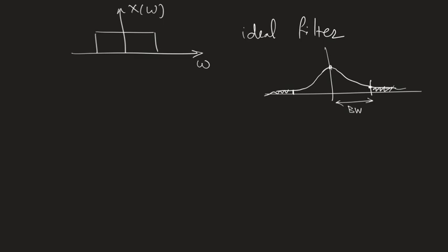Or when you discussed in your circuits the transient effect that happens due to switching on the circuit, you assume that after a couple of time constants, it decays enough such that you can assume it's no longer existing, and you are dealing with a steady state signal. You are no longer dealing with transient, because the effect of that became very small. So here also, the signal amplitudes with those higher frequencies is very small, so I ignore those parts and I only consider this as the effective part of the signal, okay?